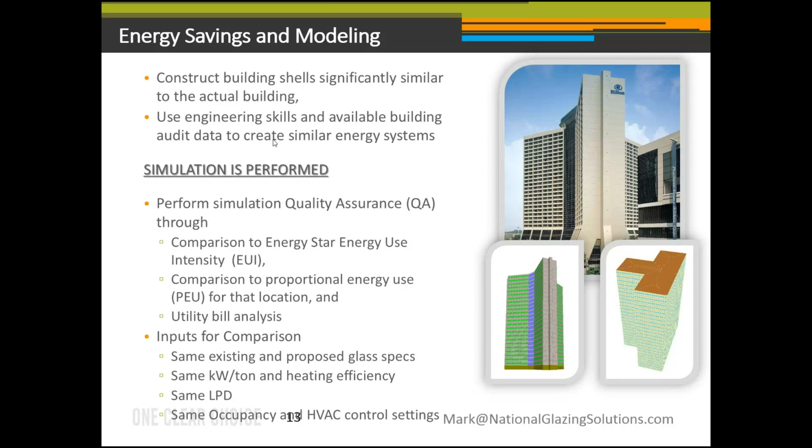Then with our own site audit and the performance of the proposed glass plus film combination like we've been discussing, now we can create a simulation. At this point, I need to address the skeptics and admit we haven't yet determined whether our simulation is right. We haven't even determined if it's reasonable. In order to check whether a simulation is right or reasonable, we still have to perform some quality assurance steps, including first comparing our results to some industry guidelines such as the Energy Star EUI.